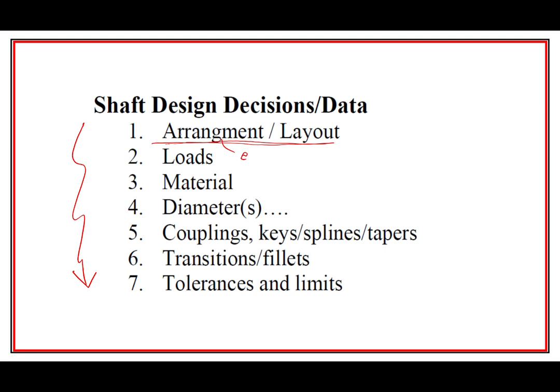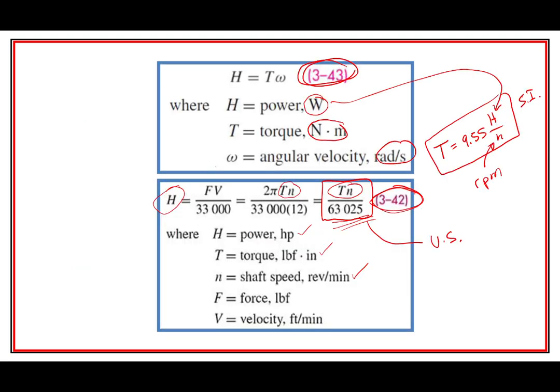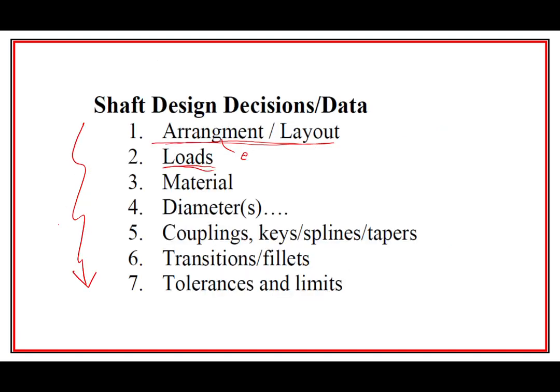And then the next, we've got to figure out what the loads are. Okay, so we just had this right here. Here's the beginning of the load section. We could get the torque, and if we get the torque, we get the force, and where the force is located, and how much they are. Once you get the loads, we need the supports, right? The reaction forces, and then you need the shear moment diagram. So that's all right here in the loads.